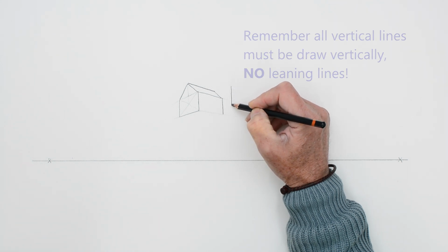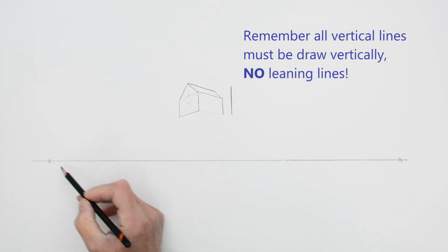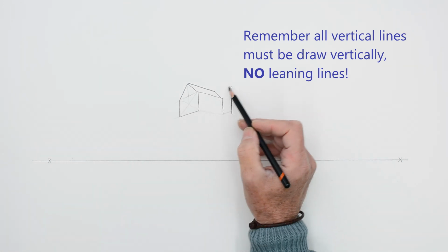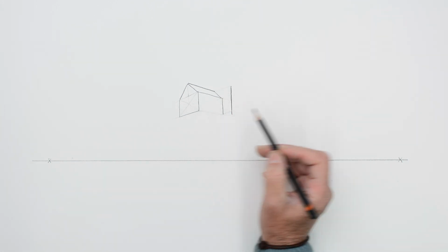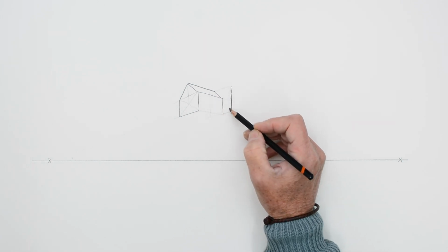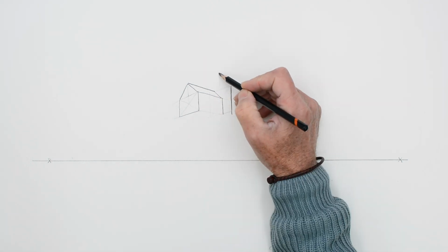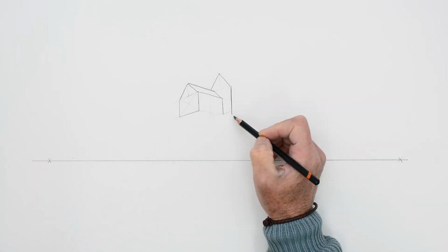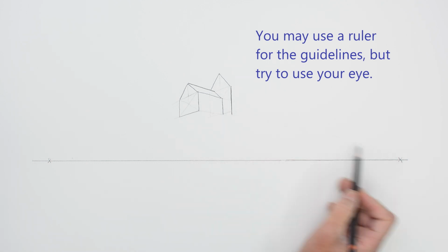I start with that first line first of all. I'm now going to draw things on the left side of that line, so it goes to the left vanishing point. See, I'm projecting it up, as you can see there. I'll draw another little rectangle as though I can see the other side of the rectangle. I can't really. Draw my cross, take the vertical, and I can then put the gables in for the side of the building. Okay, everything now to the right of the eye, you see, can go down here.